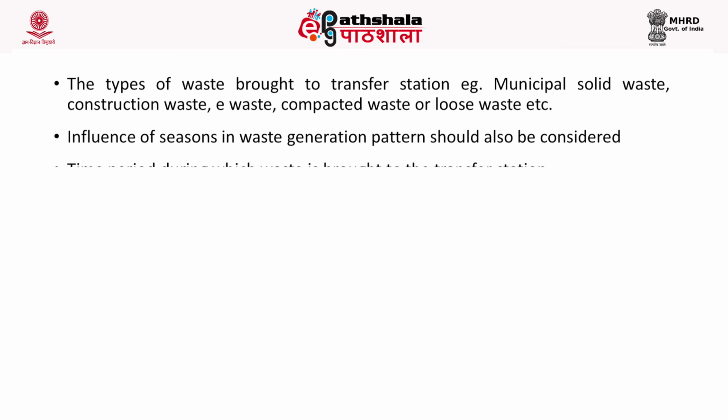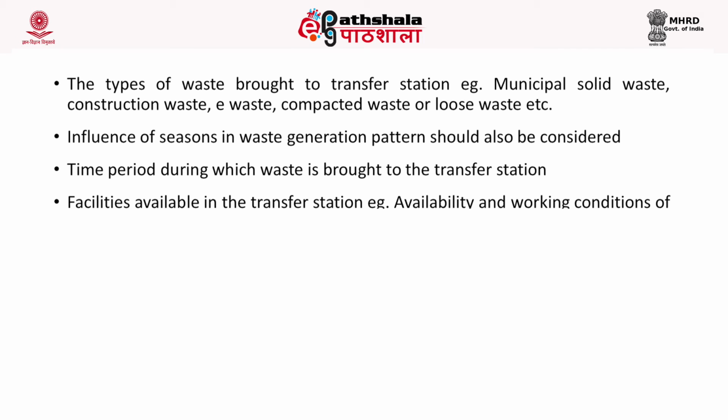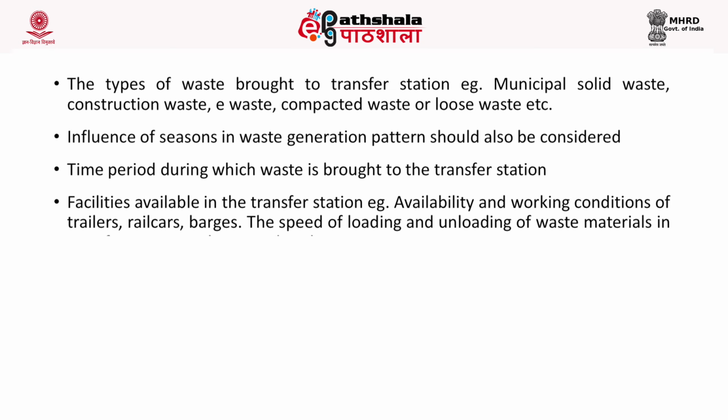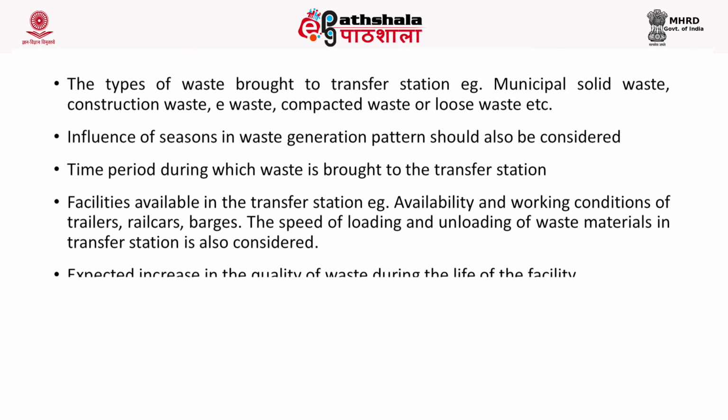Now let's look into the size of the transfer station. The size of a transfer station is planned based on some of the factors which are discussed below. First, the quantity of waste generated, and the rate at which the waste is to be delivered to the station.